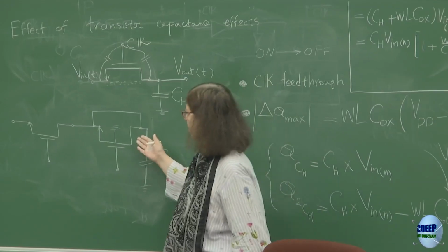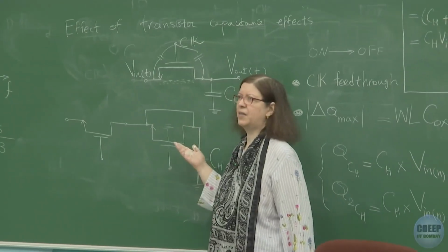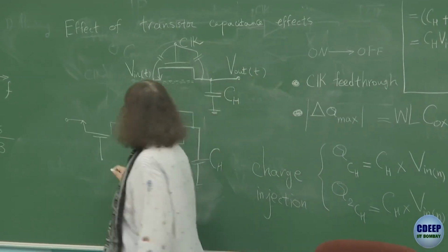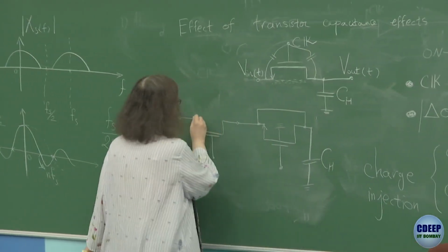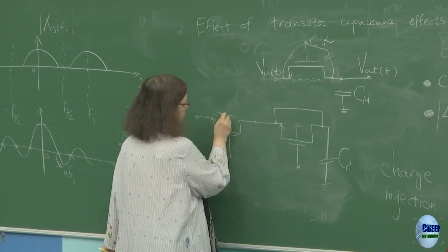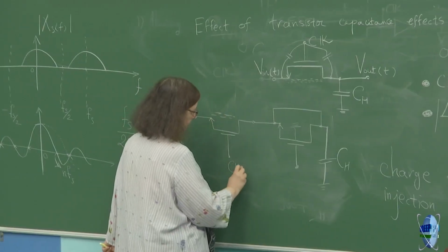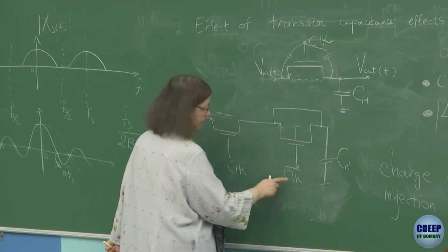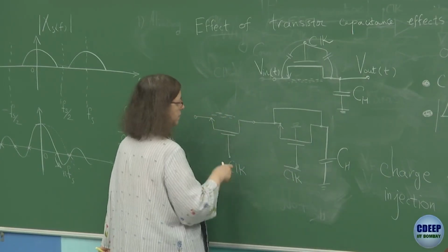And in this transistor only a channel will form. Nothing else will happen because we have already shorted the nodes. So what will happen? The channel charge which was here, say if we are giving clock here, we will give clock bar here. Again, here also we have the same thing. We have to make sure that these two are synchronized.